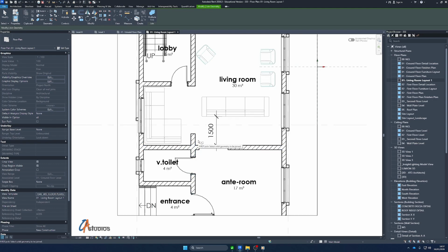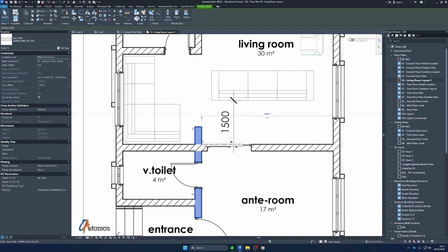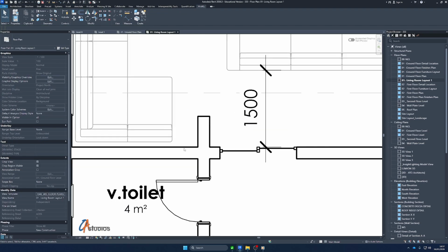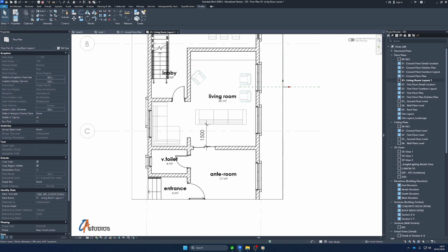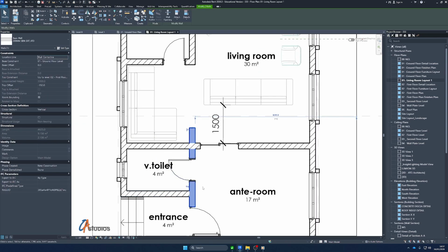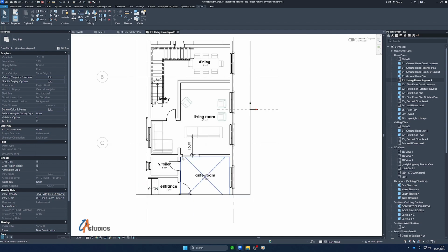Oh, okay, it did join, but usually it would give an error that you can't join the elements that's not in the design option with this. But fortunately it worked in this instance. But if you ever encounter that, what you need to do is just to add that element to your option sets, and then you can make those join the elements cleanly, or sometimes automatically do that.